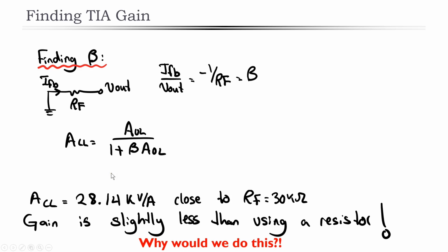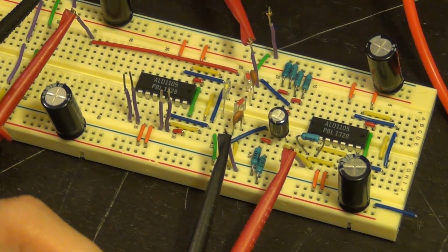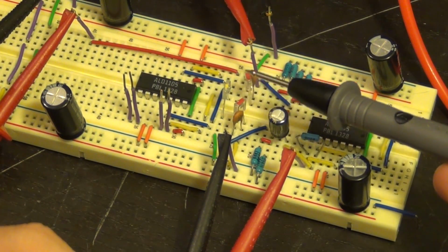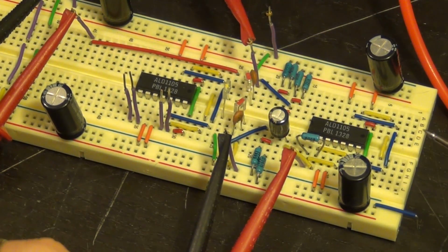In order to answer that question, we've built this circuit. So let's go back in the lab, measure it, and compare the difference between using a photodetector with just a resistor and using it with our own transimpedance amplifier, and the difference will become very clear. So here we're showing our final setup. We have 2 photodetectors here and a transmitter, and we built both of the transimpedance amplifiers that we described.